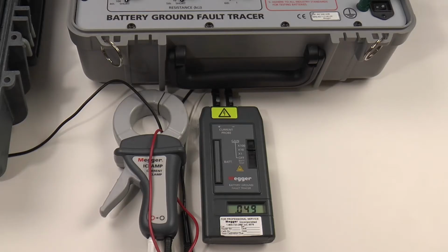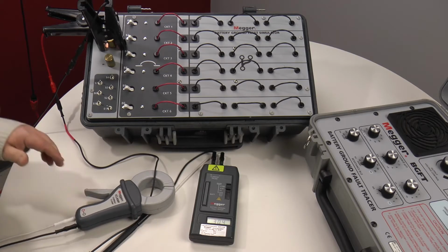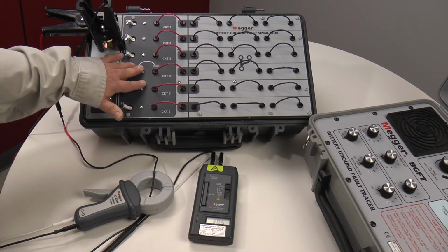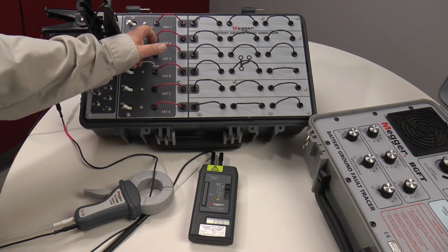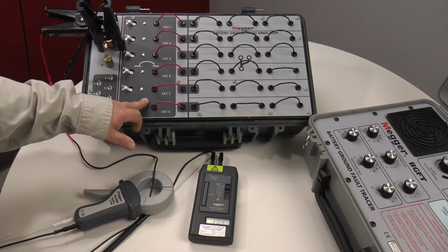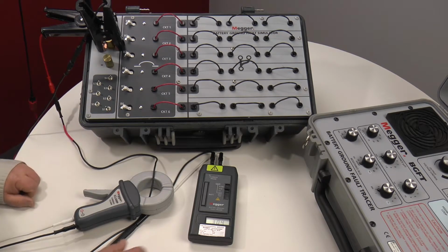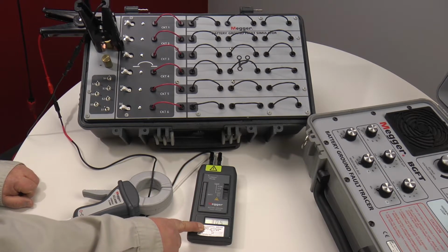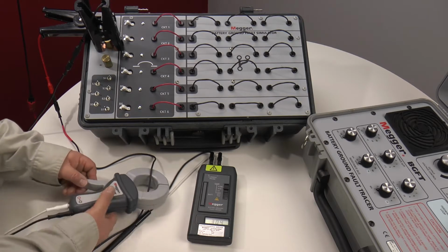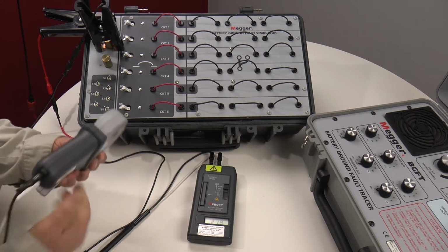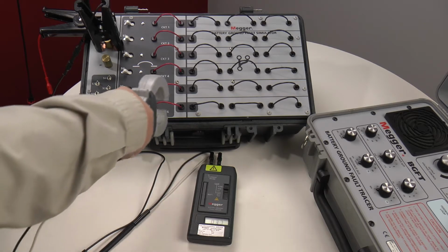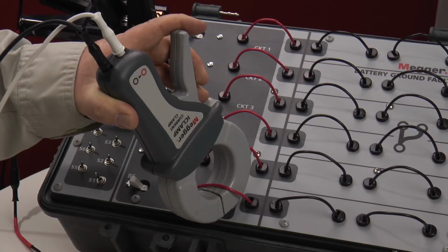If the majority of the fault current drops when adjusting the resistance, the fault is primarily resistive, and we can proceed and trace the fault. To trace the fault, we go to the panel and we measure the fault current in each circuit. We want to find the circuit drawing the most fault current. We will then trace this path to locate the fault. See what the total is on the receiver and take measurements on each circuit on the panel.